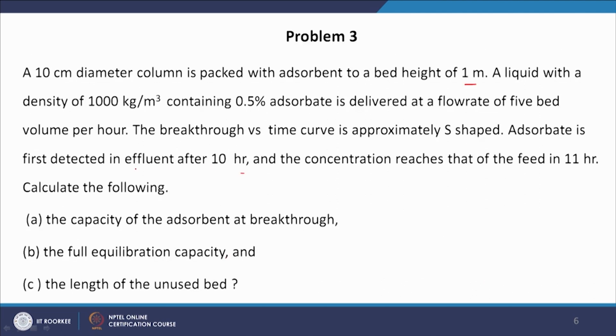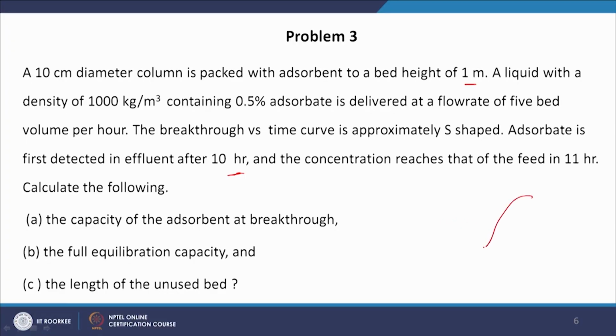Here, adsorbate is first detected in the effluent after 10 hours. So, the capacity of the adsorbent at breakthrough, this is our breakthrough, and the concentration reaches that of the feed in 11 hour. So, we will be having this type of graph. So, this is our 10 and this is our 11. So, this will be half of that, so 10.5. So, 10.5 hour we will be considering as the time taken to completely exhaust the bed.